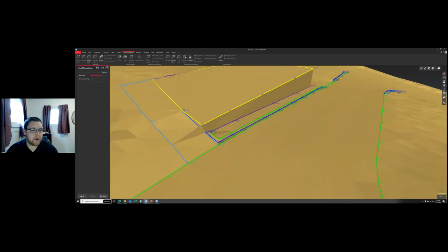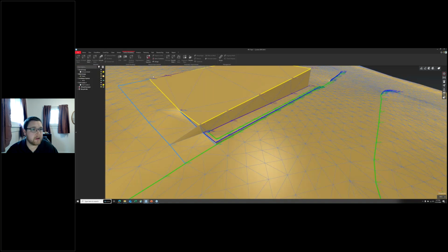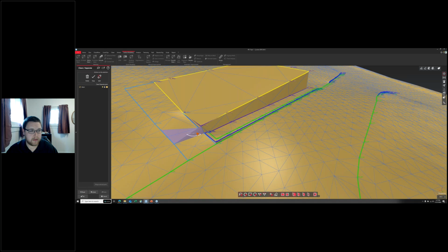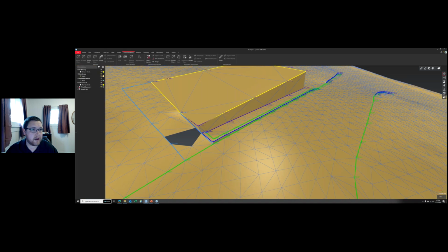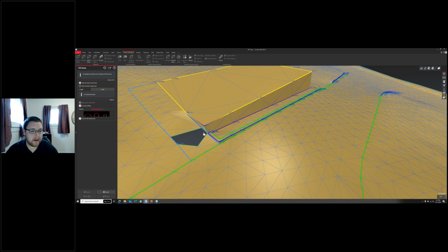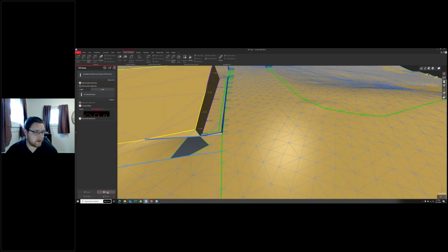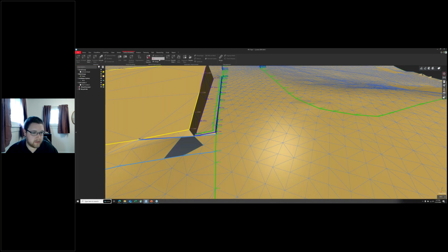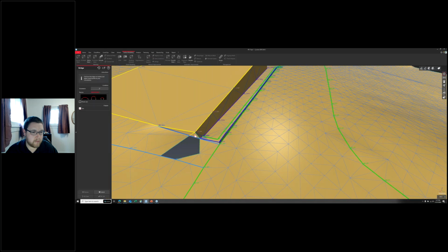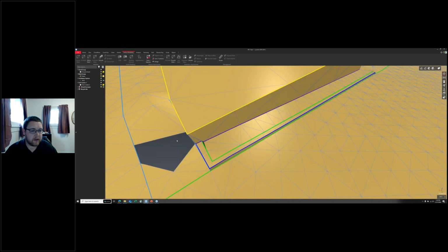So what I'll try there first is smooth. That didn't work. So what we can do is delete them, and then I'm going to do that fill hole command now. I'm going to try to fill this hole, but it has that point over there. It actually looks like